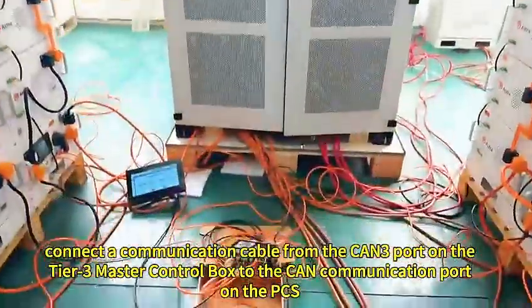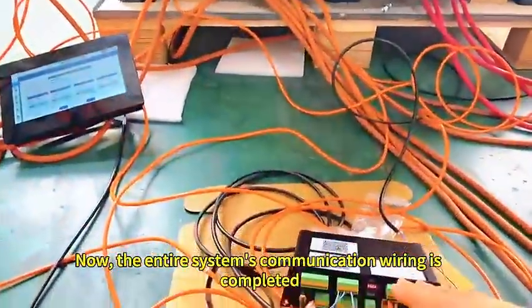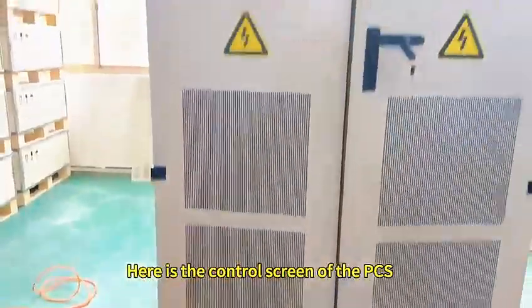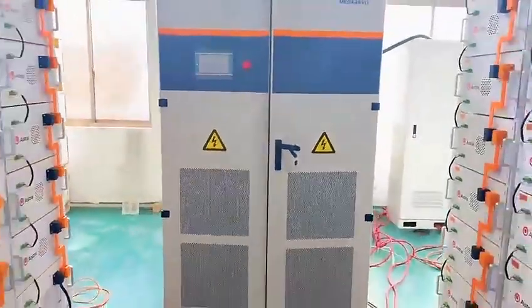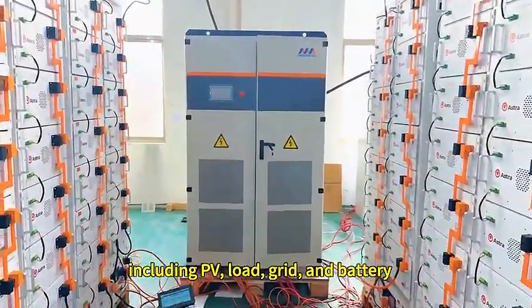Next, let's connect the lithium battery groups to the PCS. Connect a communication cable from the CAN3 port on the Tier 3 master control box to the CAN communication port on the PCS. Now the entire system's communication wiring is completed.